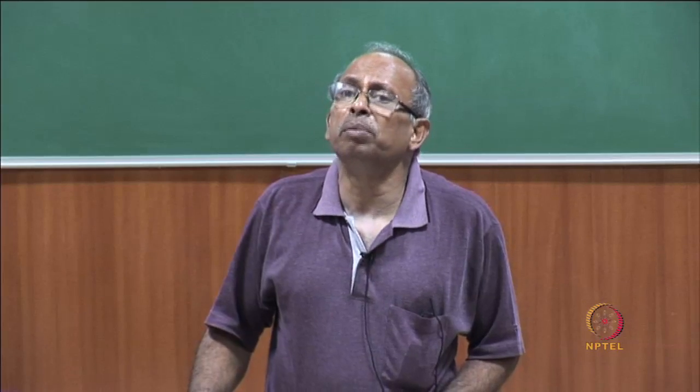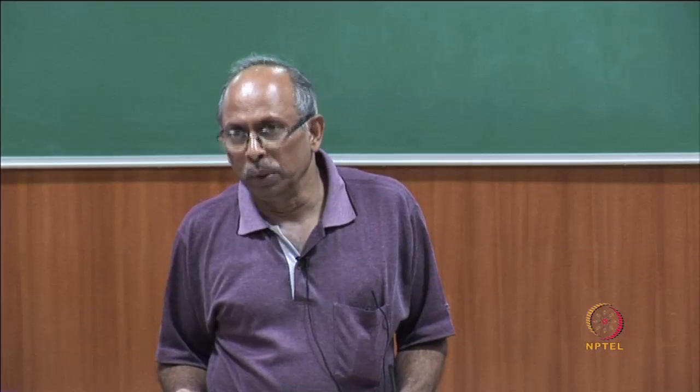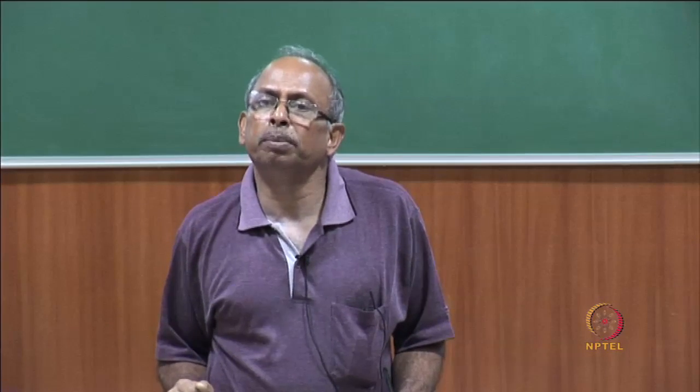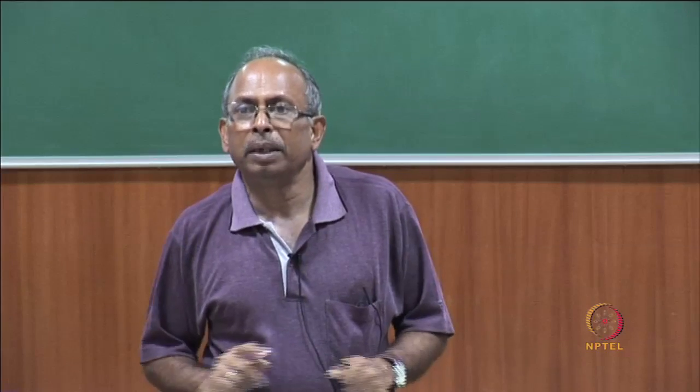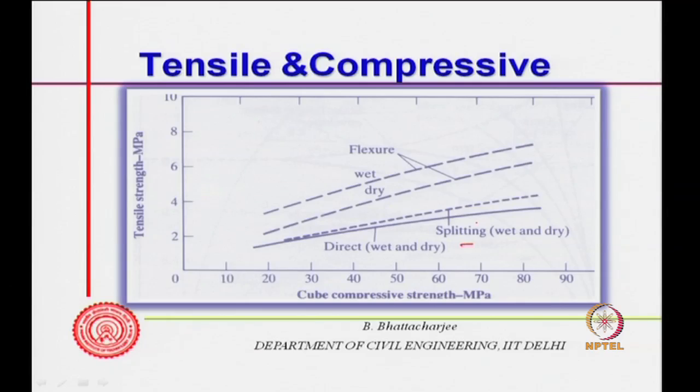It is of course difficult to measure direct tensile strength, although there are some attempts to do it now. Most commonly we measure by a specific method called the split tension method, or split cylinder method, which gives you some indication of the direct tensile strength.